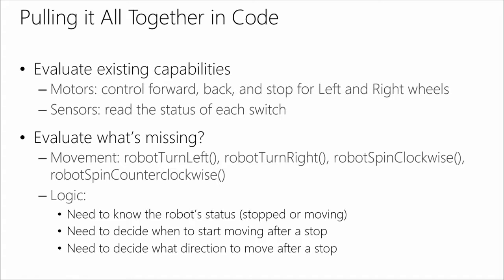We're adding all that logic that says, okay, I want to be able to spin 360 degrees, or spin counterclockwise for half a second, or do this, or do that. If you write your code smart enough, then you won't get stuck in a corner. It's going to go into a spot and try to back up, but it needs to turn a certain way. So depending on which of the sensors is up against the wall, it's going to take that into account.